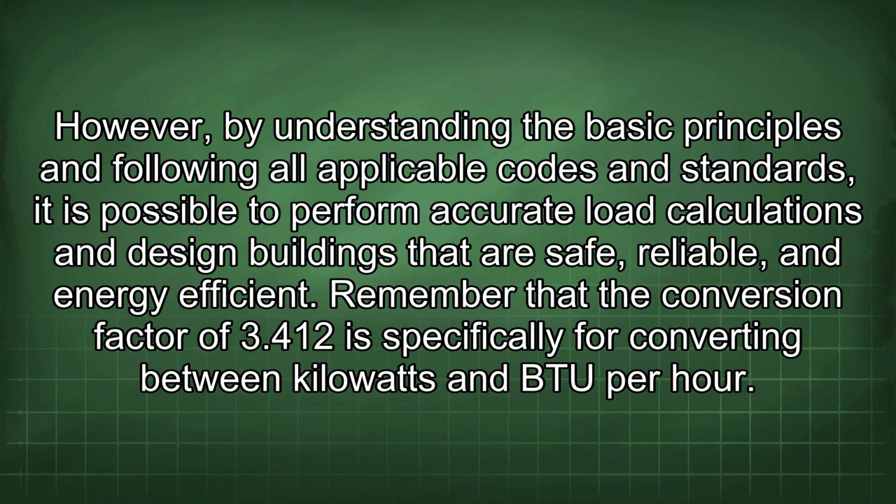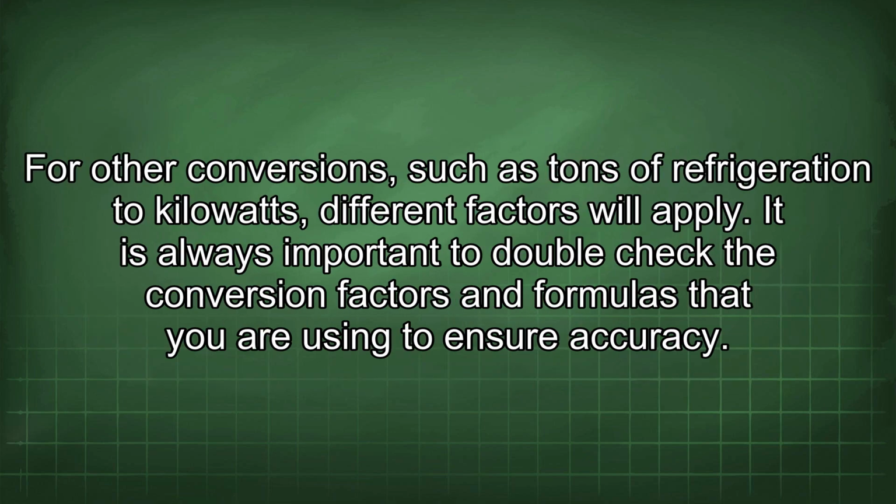Remember that the conversion factor of 3.412 is specifically for converting between kilowatts and BTU per hour. For other conversions, such as tons of refrigeration to kilowatts, different factors will apply. It is always important to double-check the conversion factors and formulas that you are using to ensure accuracy.